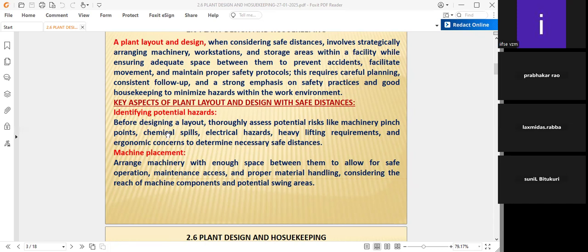Chemical spillages, because from the stores department, our raw material storage, to the process department, the distance is more in orientation, we can't avoid it. Therefore, in the process department itself, some small service storage will be taken care of. For example, furnace oil: the main tank is one, where the pipe is directed to the process department, where the boilers are, where the service tank is also there. From the main tank, it will go to the service tank.